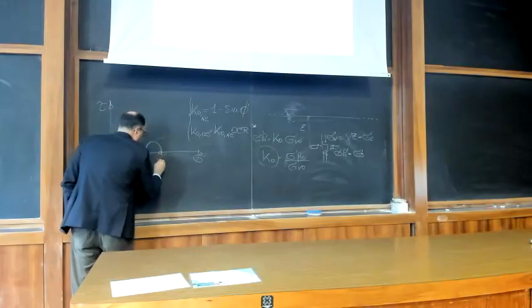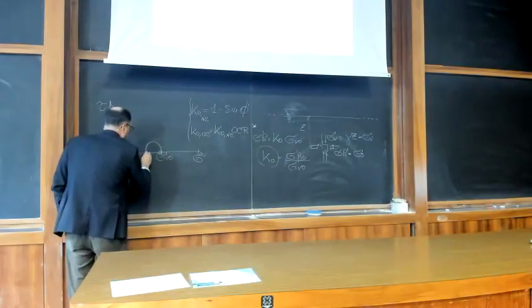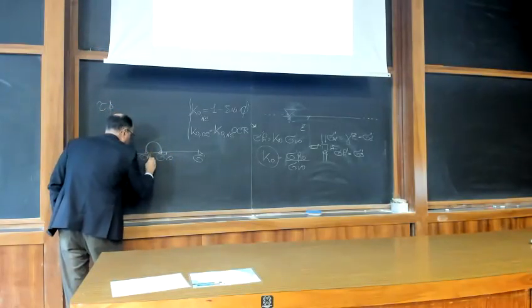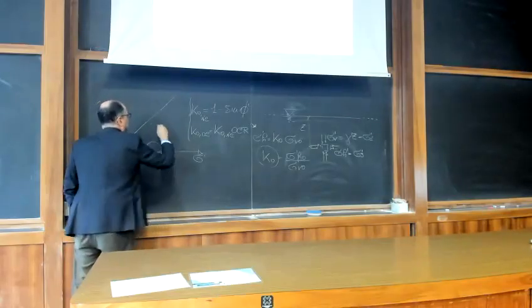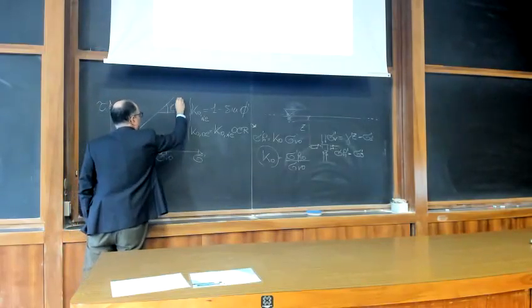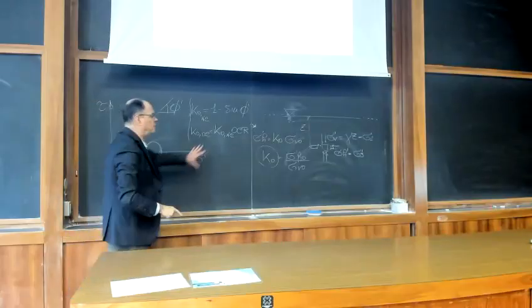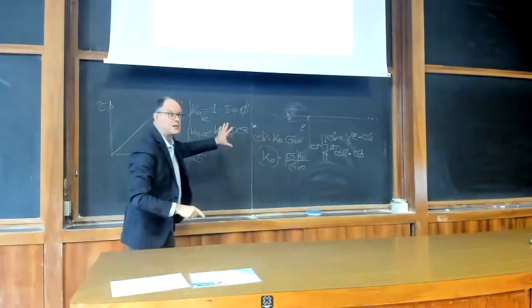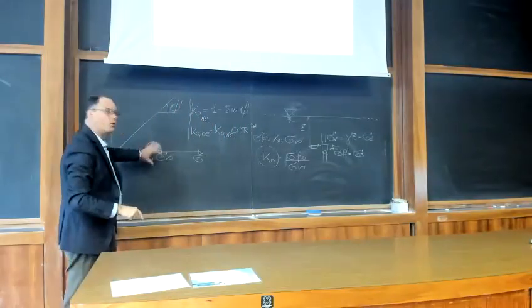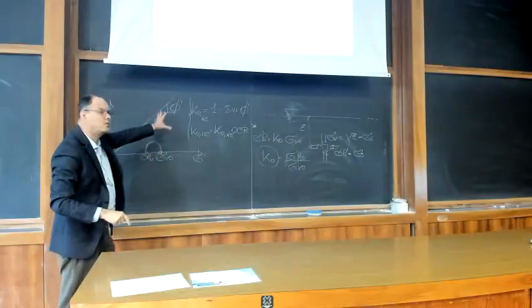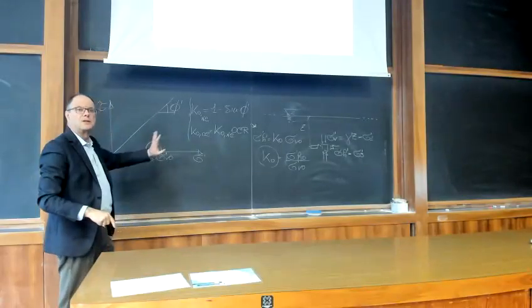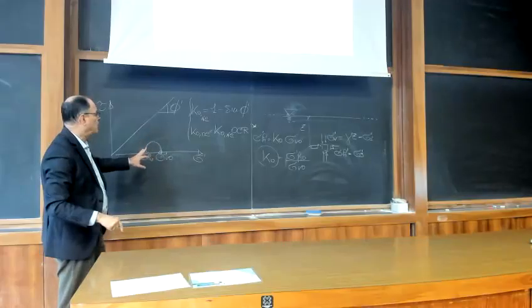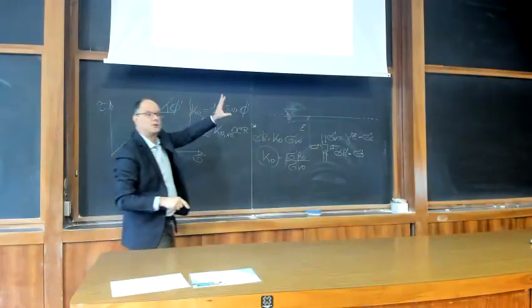So you have your vertical stress and you have your horizontal stress, and somehow you have your limit line inclined by phi. Okay, this is your initial condition defined like that, and as I said, unless you know K naught, you don't know this Mohr circle. Let's assume that you know K naught, you know the horizontal stress, this is your initial point. Now, how can you get to these two limit conditions?